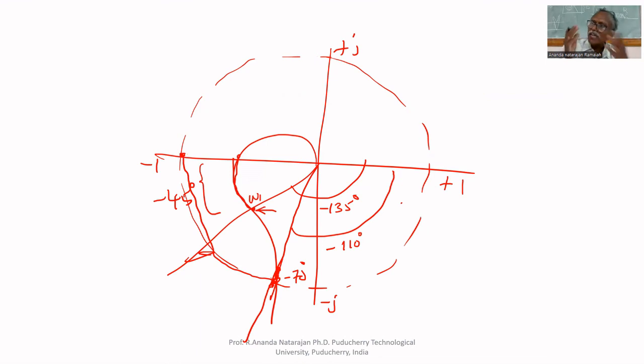So if I introduce phase shift also, the system becomes marginally stable. When it crosses minus 1, the system becomes marginally stable. But I am not increasing any gain, I introduce only phase shift. Because of that phase shift, it becomes unstable.